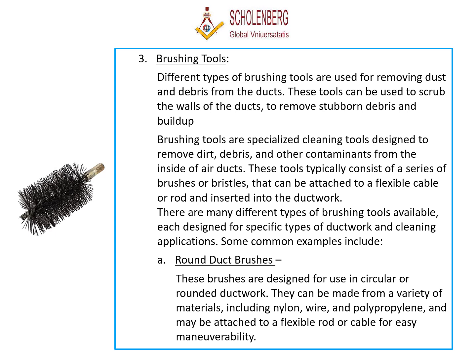3. Brushing tools. Different types of brushing tools are used for removing dust and debris from the ducts. These tools can be used to scrub the walls of the ducts, to remove stubborn debris and buildup. Brushing tools are specialized cleaning tools designed to remove dirt, debris, and other contaminants from the inside of air ducts. These tools typically consist of a series of brushes or bristles that can be attached to a flexible cable or rod and inserted into the ductwork. There are many different types of brushing tools available, each designed for specific types of ductwork and cleaning applications. Some common examples include: